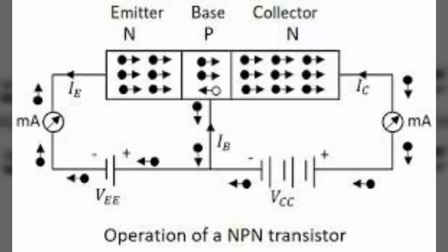Okay, now we will discuss the working of NPN transistors. The forward bias causes the electrons in the n-type emitter to flow towards the base. This constitutes the emitter current IE. As these electrons flow through the p-type base, they tend to combine with the holes to constitute base current IB. The electrons which combine with holes become valence electrons, and then as valence electrons they flow down through holes and into the external base lead. This constitutes base current IB.